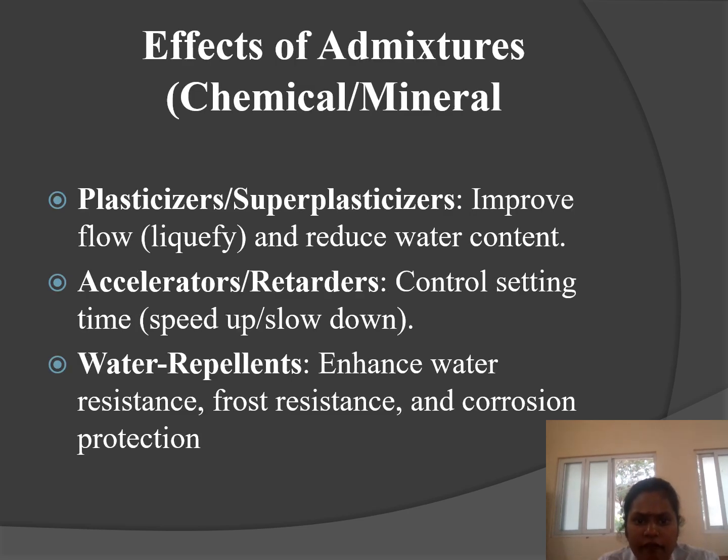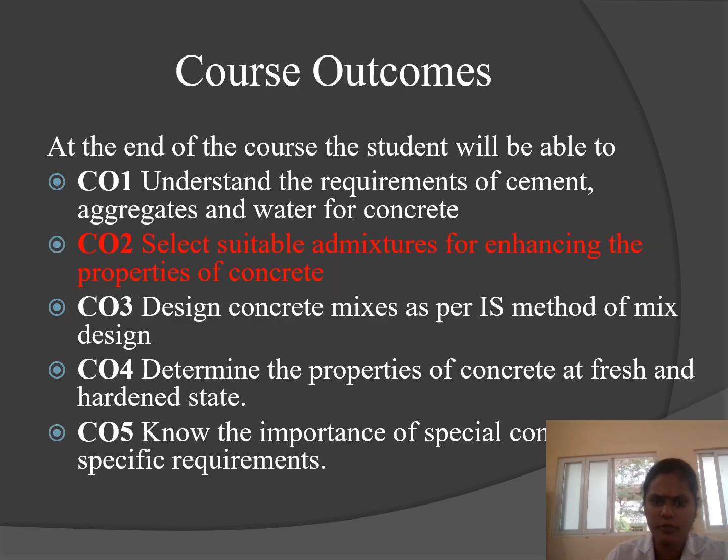Next is the effect of chemical admixtures, chemical and mineral admixtures. Plasticizers and superplasticizers improve the flow and reduce the water content. Accelerators and retarders control the setting time. Next is water repellent: it enhances water resistance, frost resistance and corrosion resistance.